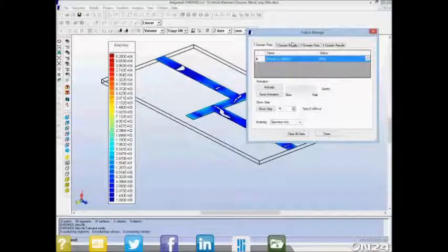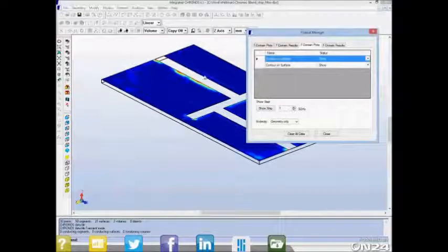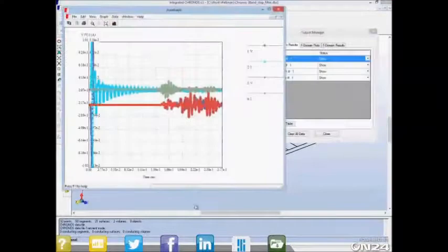By doing a Fourier transformation, it's also possible to take your time results and transform them into frequency domain results. So in another tab of our outputs here, we have some plots defined, and here we can show plots of the electric field which are related to specific frequencies, 5 gigahertz, 6 gigahertz, and so on, again by doing a Fourier transform. Other things that are pulled out automatically include numbers like the voltages at the ports that are used to define the pulse.